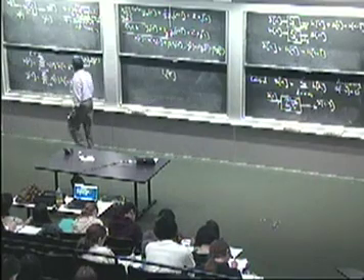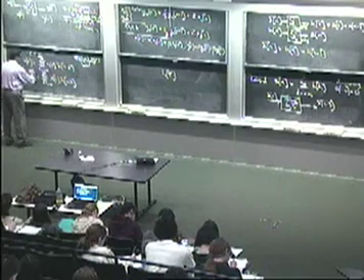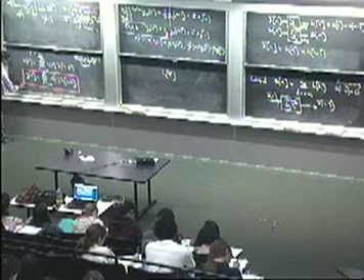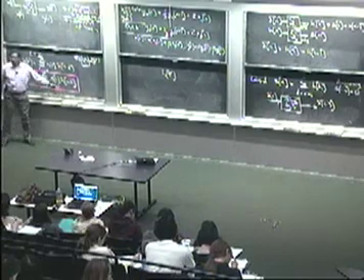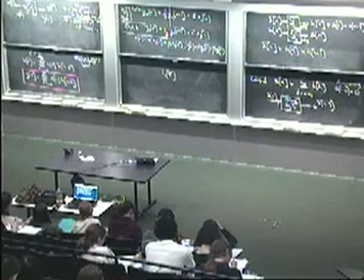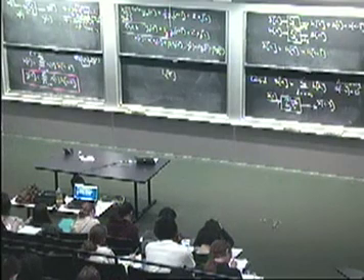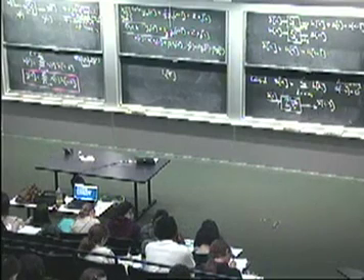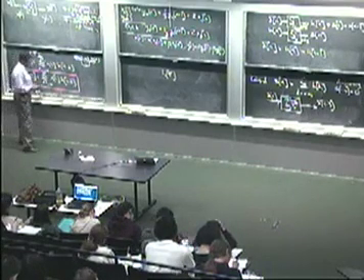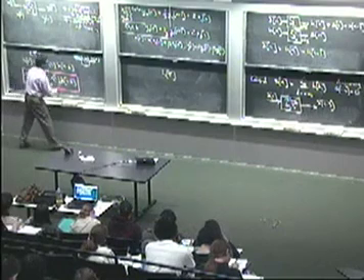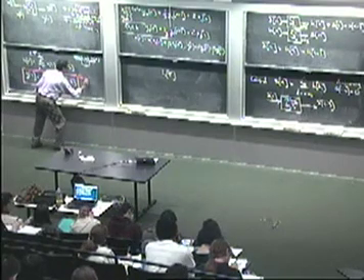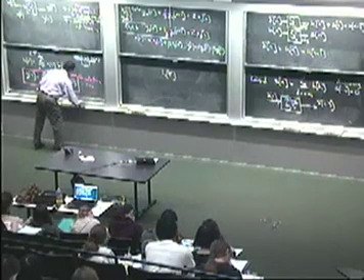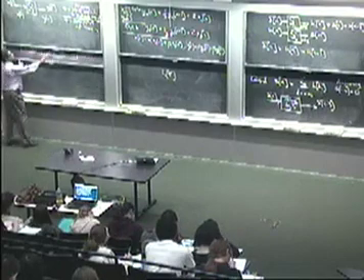So what have we been able to do? We've been able to write down what the output looks like for an arbitrary input in terms of the unit sample response. If you give me the unit sample response for an LTI system, I can write down the general response, the response to a general input. And this is what we refer to as a convolution, or a convolution sum. Okay? That's a convolution.